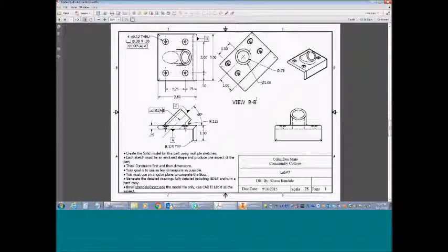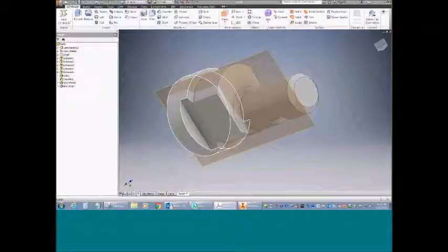I came up with this one specifically for planes, so that they were forced to use planes, and also forced to use an auxiliary view in their detail drawings. We also introduced some GD&T in this one, in so much that they have to duplicate these feature control frames and some of the basic dimensions. So in the detail drawings for this one, we would be detailing all these out in orthographics.